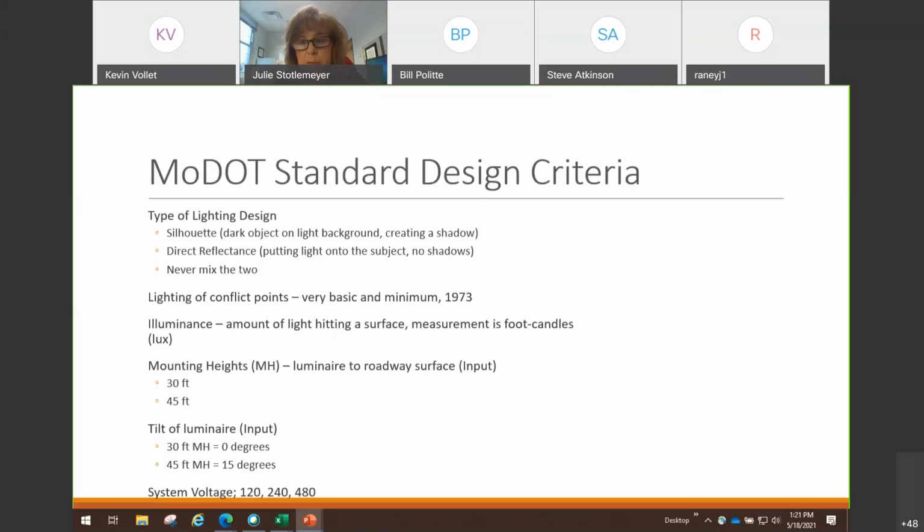Voltage is another item you're often asked about, especially with LEDs. Voltage can be used to drive LEDs harder, but as we do that, we degrade the life of that LED. So you want to be careful. A lot of times manufacturers can tell you they can meet the light output, but what they might do is put a lot of voltage behind that LED to really drive up the output, and then they degrade the life of it. And a lot of times the drivers that go into the mechanisms of the light are affected too.